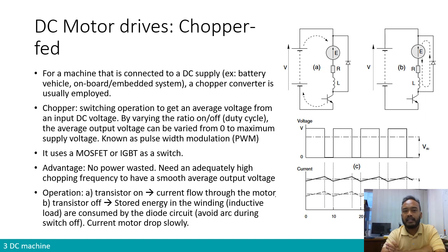The thyristor is, I would say, less and less used. It is almost for older applications because it consumes more energy. In the power electronics part, the driver part, using a chopper is much better. So therefore, in an inverter type of driver, usually we have a rectifier using power diodes, and then a PWM circuit part to adjust the level of the DC voltage.